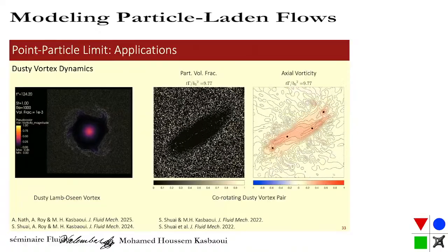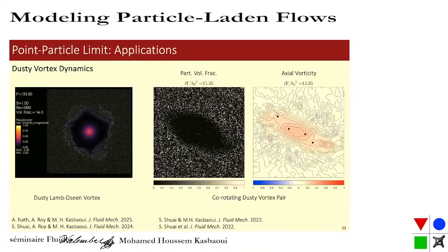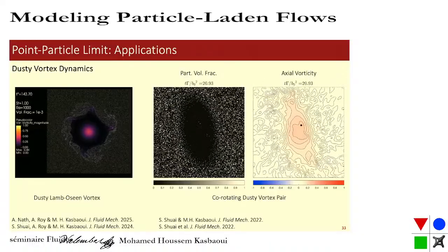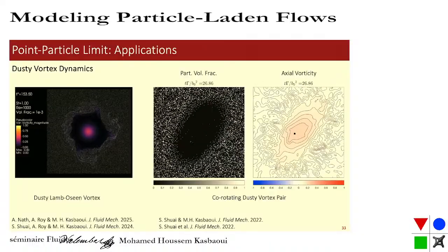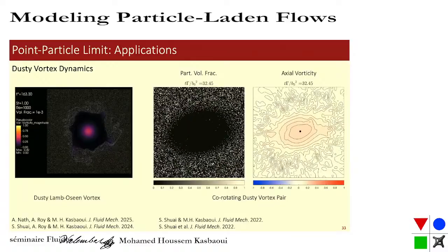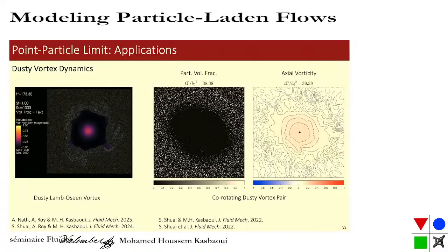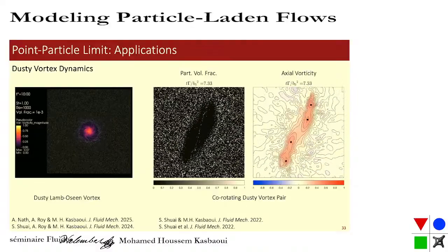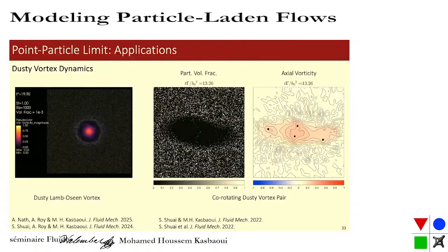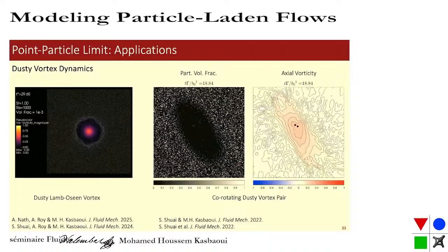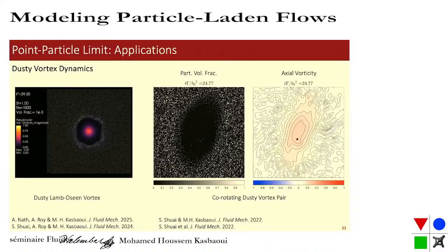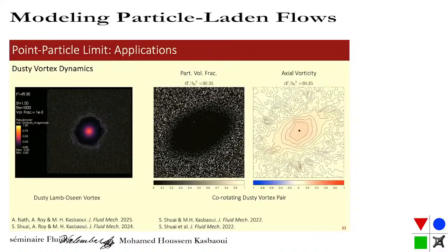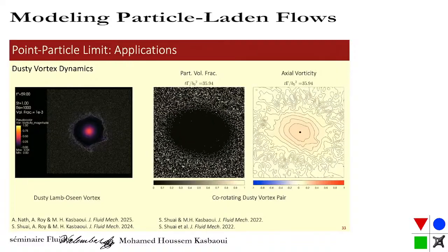So that's vortex cores. We noticed that each vortex gets split into two little vortices due to this deformation caused by the particles. So they get split, and then the inner vortices merge first, and then the outer vortices merge second, something like that. And it is very dependent on the Stokes number.